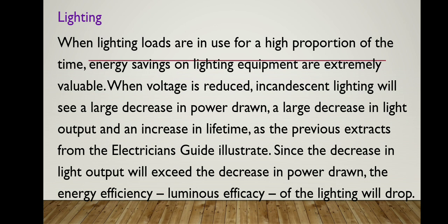When voltage is reduced, incandescent lighting will see a large decrease in power drawn, a large decrease in light output, and an increase in lifetime, as a previous extract from the electrician's guide illustrates.